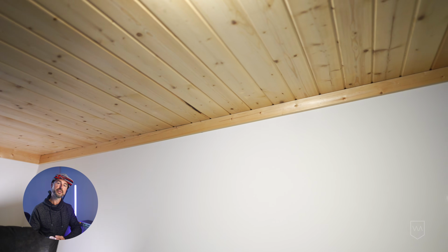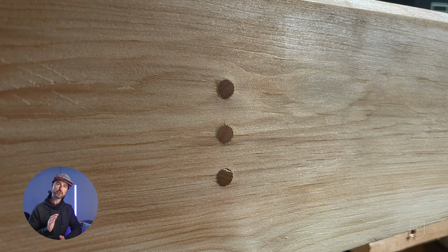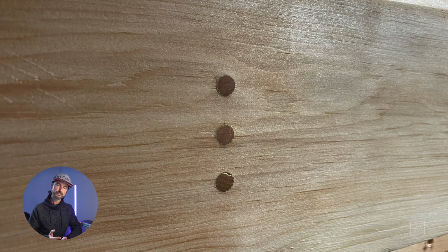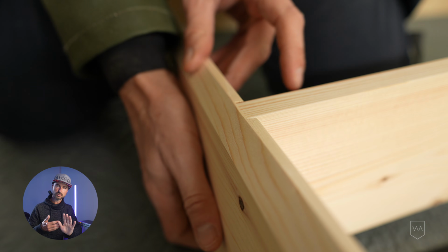A couple things about the ceiling cloud. Thomas and I talked about it, and we wanted to spend a bit of time and a bit of budget here because we wanted the ceiling cloud to be a real feature piece, a real statement piece. Thomas's room has these really beautiful tongue and groove pine paneling on the ceilings, and I wanted to accent that with a ceiling cloud. I came up with a really nice ceiling cloud design that uses all wood joinery. There are no screws, no nails, no fasteners in the ceiling cloud. It's all done beautifully with spline joints or dowel joints.